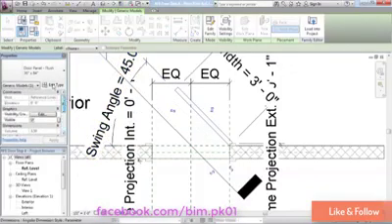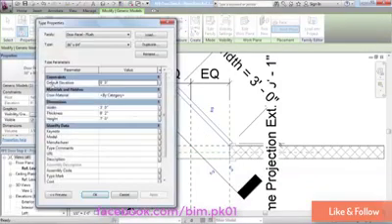And you will also see edit type, as you might expect, and other properties here. When you're in the family editor and you go to either the properties dialog or the edit type dialog that we're in right now, there'll be a third column over here. And several of the parameters have these little tiny buttons. Any parameter that has a little tiny button in the far right column, you can link that parameter up with a parameter in the host file. So you can use a parameter in the host file to drive the underlying value in the nested family.